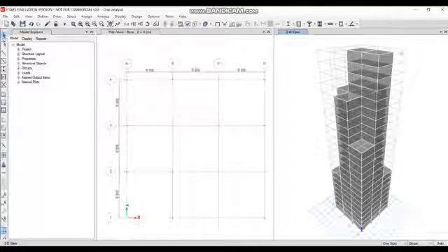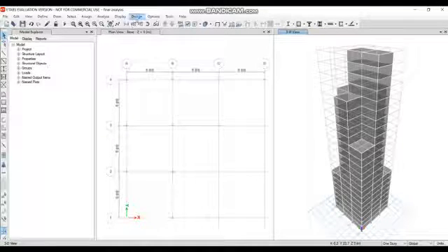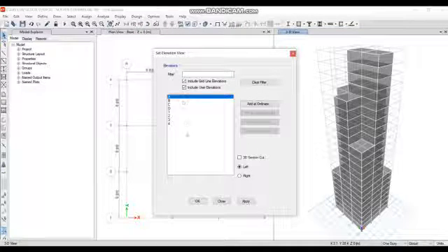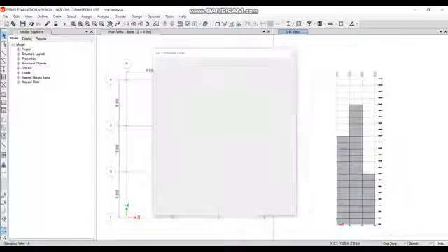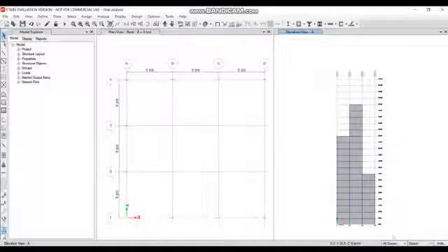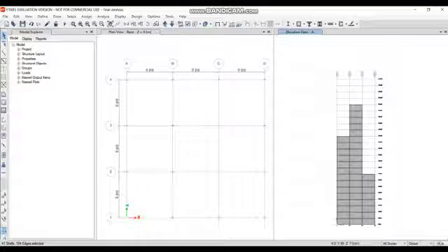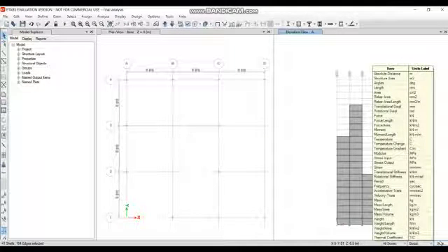Now go to the elevation option, select the A, click on OK, select all stories option, select the shells. You can see Table 4 from the IS 1875, as it will give the different loading options.